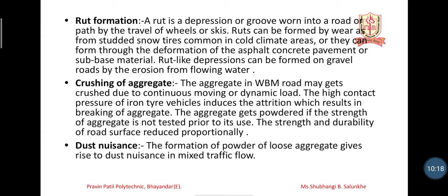Then the next problem is dust nuisance. The formation of powder from loose aggregate gives rise to a dust nuisance in mixed traffic flow. As you can see in village areas in the summer season, there will be a dust nuisance because the aggregate has been crushed, or because the soil is not compacted or watered properly. If you are not compacting or watering the soil properly, then obviously a dust nuisance will be formed when a vehicle is moving through that area.